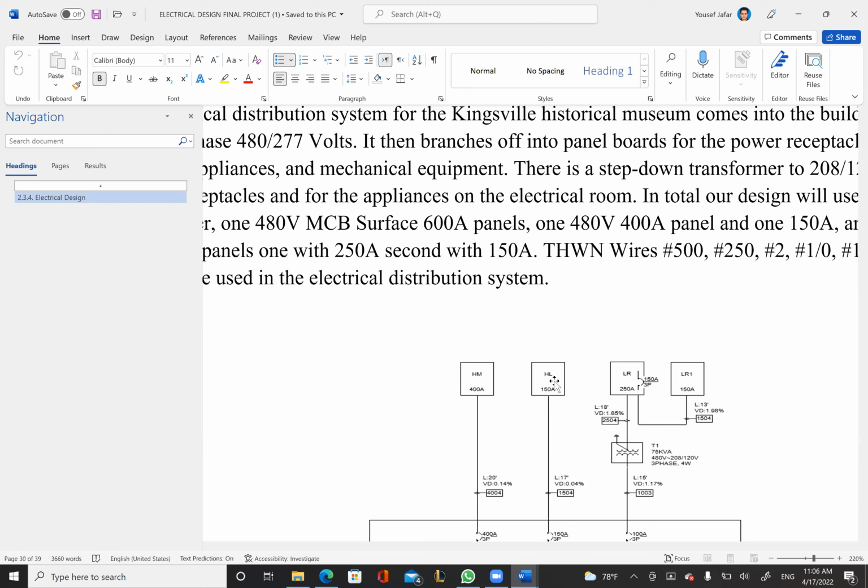One is residential, and the other is non-residential, which is commercial. So for that, according to NEC code, we have to take 3 kVA, unless you go facility by facility, room by room. So let me pull out that NEC code, the specific article, so you will see. Hold on, I will just pull that out. Okay.